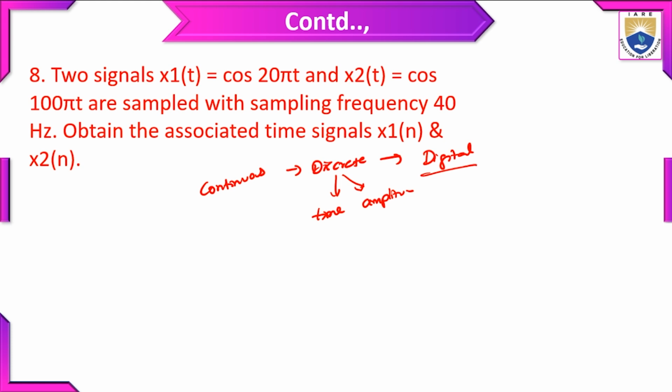So in analog pulse, we are doing only half. You discretize in time only, not in amplitude. That's why it is analog pulse. In analog pulse schemes, you have pulse amplitude, pulse width, and pulse position. Whereas in digital, you have PCM, DM, DPCM, ADM, like that.